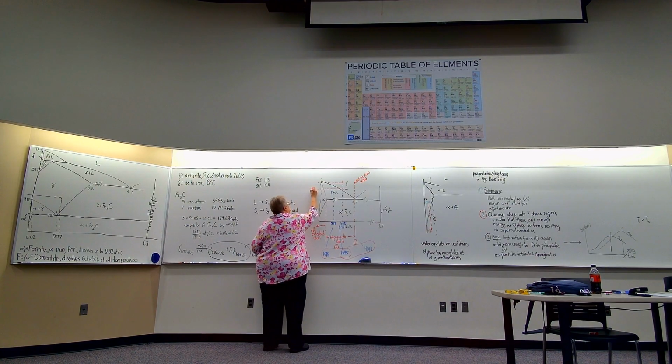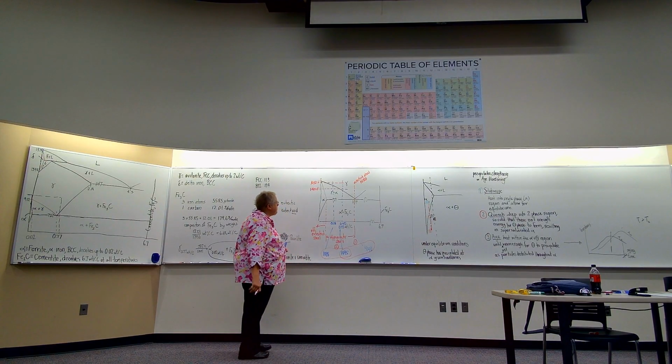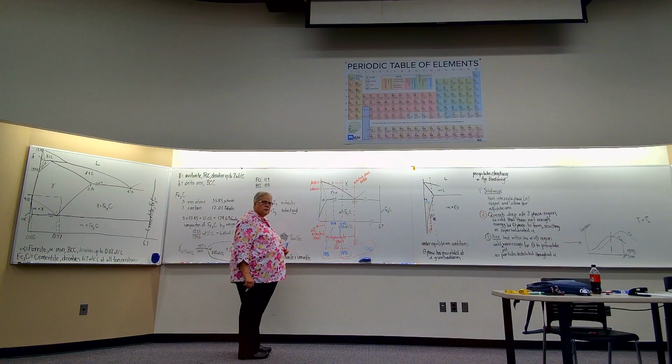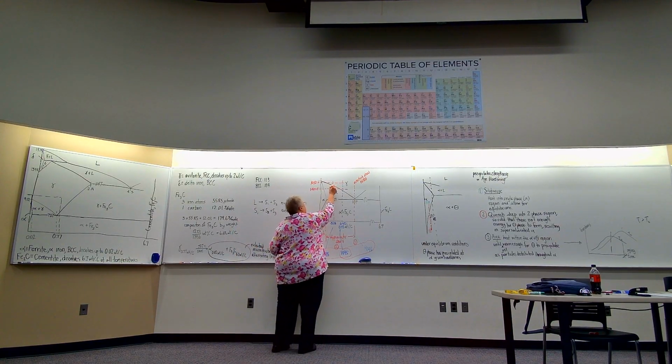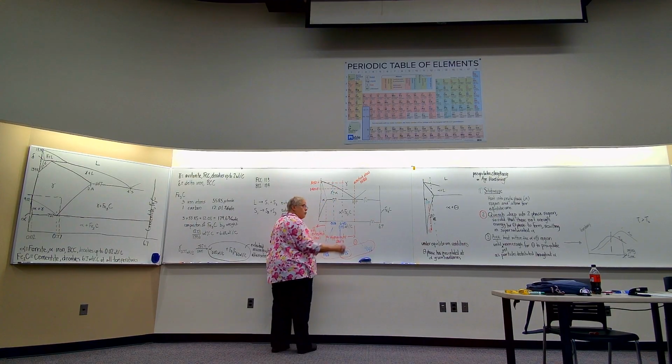So this is about 1400 Fahrenheit and 1650. We're going to heat those steels to one of these two temperatures and then water quench.